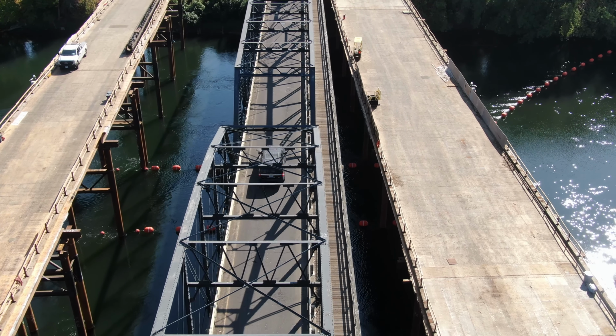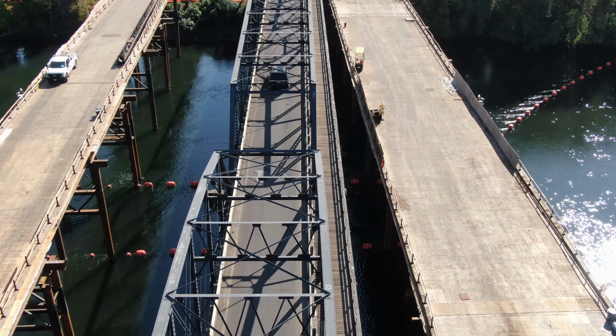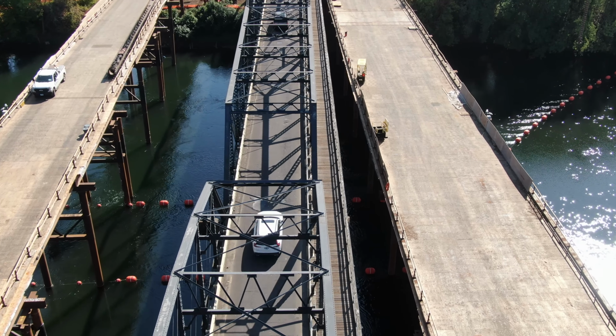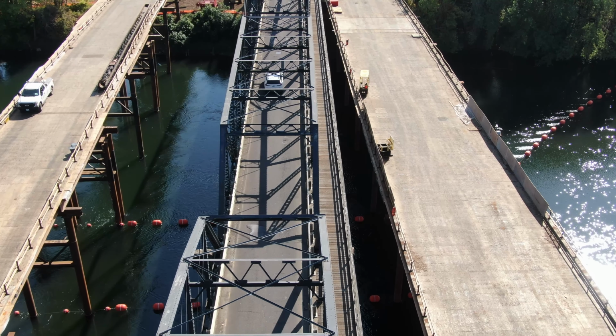In some ways, wind loading becomes the enemy of seismic loading. With wind load, you're trying to get these high wind loads that drag on the strut down to the bearing, and by stiffening and bracing the vertical members, you can bring that load down to the bearings.